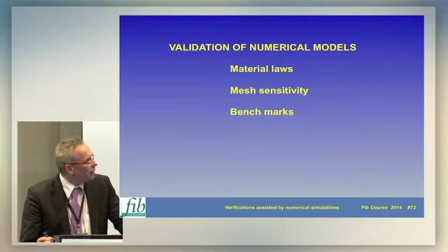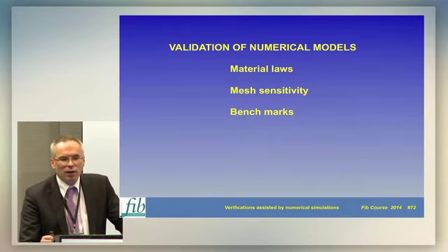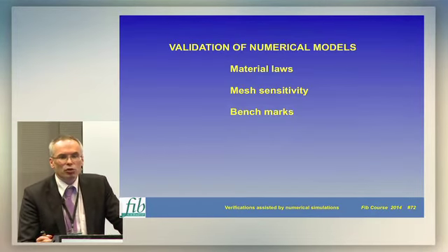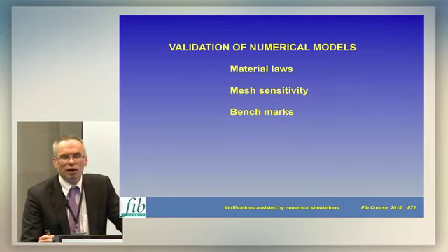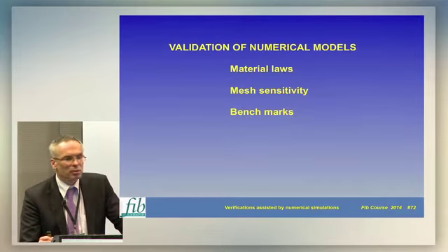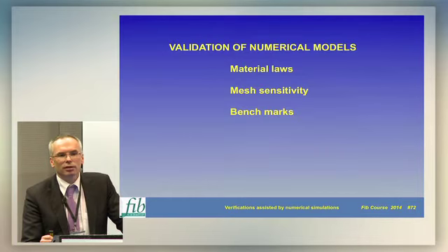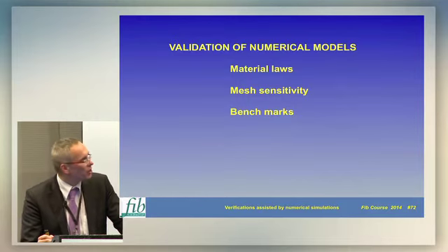Then, when modeling with finite elements, there will always be an issue of mesh sensitivity. So every engineer using nonlinear analysis to model a certain structure should make some sensitivity study, and should at least use 2-3 models to evaluate the mesh sensitivity of the model.